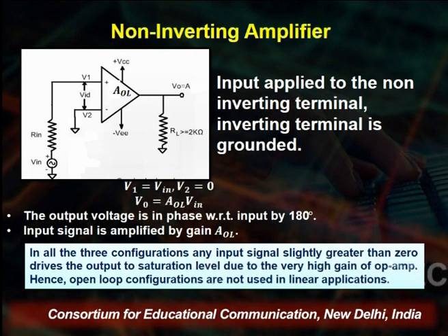So the same amplifier can be configured. In this case, the op-amp can be configured to behave as a digital or an analog component. When the op-amp is configured in open loop configuration, it works at plus saturation and minus saturation, that is, at saturation and cutoff, and therefore this op-amp behaves as a switch. In the active region, as we'll see later on, the op-amp behaves like an amplifier, but for that there is a requirement of a feedback.